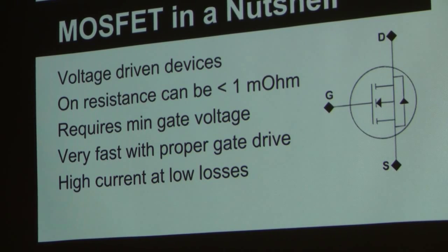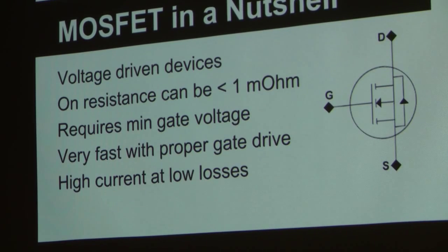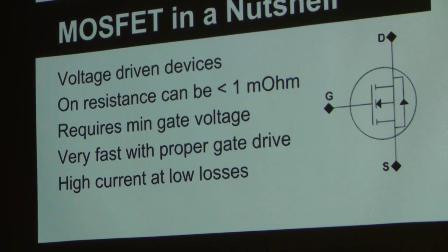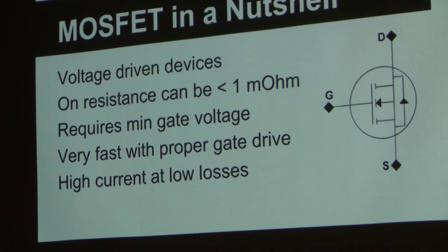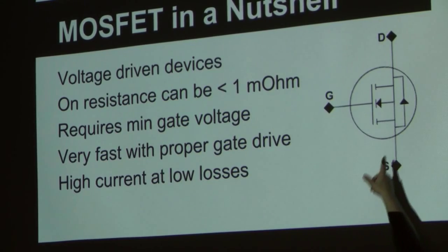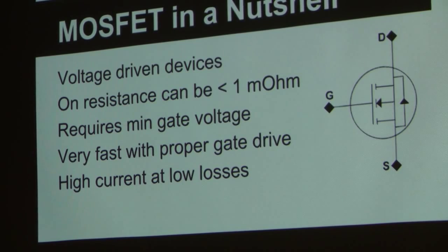That diagram has the internal workings of the MOSFET shorted. Not the diode, the MOSFET. The internal workings of that MOSFET are shorted. You're right, that symbol is an error. I did not catch that. That bar there should not be there. The topmost bar should not be there. That should be open. But I think I've got another circuit there. It's just a little drawing here.